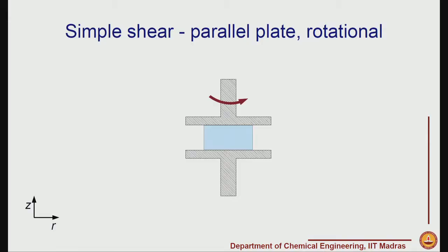we will never do planar shear flow, but like he mentioned earlier, we could do rotational or what is torsional flow. So, in this case we take fluid in between the platens, and now this is a circular cross section. So, therefore, cylindrical coordinates r and z are used to describe this geometry, and one of the platens we can rotate. So, now fluid does not have to really go anywhere, but it is being sheared. Now, the bottommost layer will remain stationary because the bottom plate is fixed. The topmost plate will have velocity which is r omega, depending on the distance from the origin as well as whatever is the omega, which is the rotation rate.